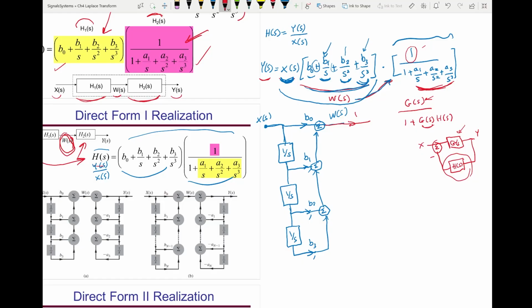So this times 1 is just this. And what is this 1? This is an integrator amplified by A1. And look here, this is negative. Since I'm using positive summation, I will then put the amplification negative. And then I have a second integrator amplified by A2. Again, because when we derive this equation we have this negative, I'll just make it minus A2. And a third integrator multiplied by A3, so that's minus A3. And I have here plus, plus, plus, so I add all these terminals.